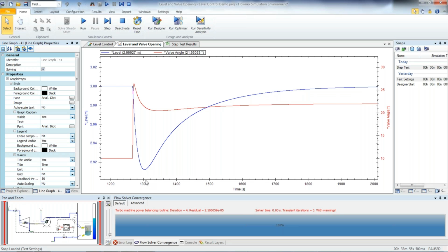We made a change at just before 1300 seconds, and we see it return almost back to the original value by 1500 seconds, back to its original value only a few hundred seconds later. So this controller appears to be performing well. We don't see any oscillations, and this response is relatively fast considering the delay inside of the process.